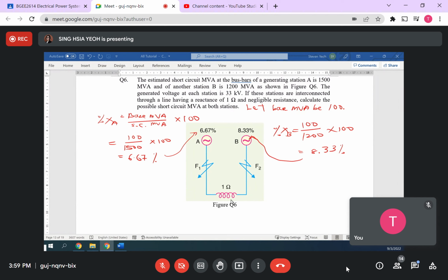So it's a bit tough to breathe in the mask. Okay. Where are we? Reactance of interconnected. So reactance percent x for 1 ohm, then component. You need to use a formula kVA multiplied with the x value over kV squared, because this is in actual, so you need to change it to percent. The formula given is kVA. Now they say 100 MVA, so you need to substitute 100 MVA.